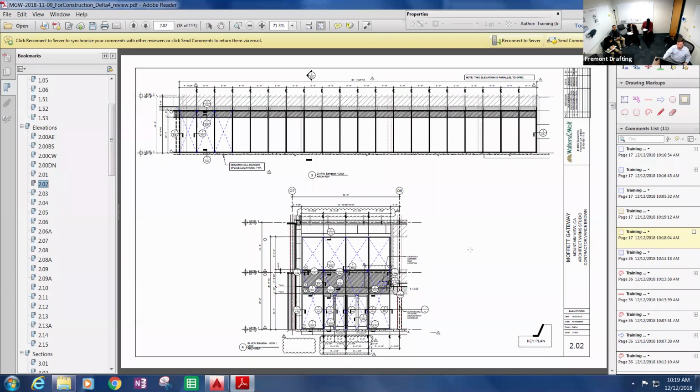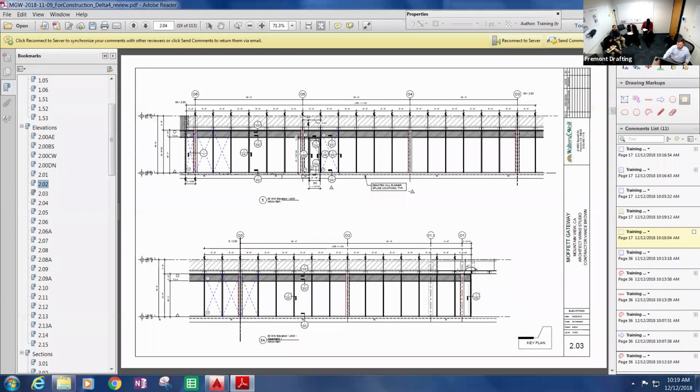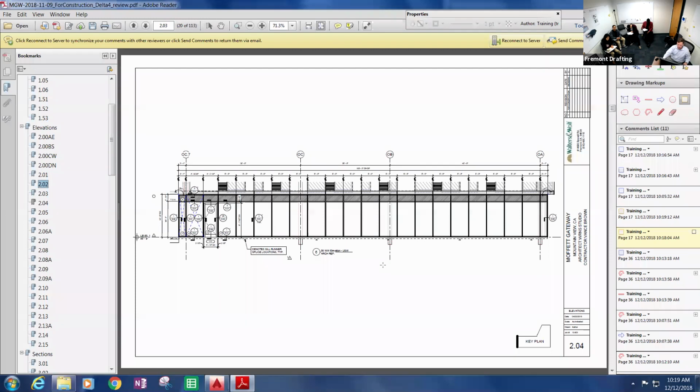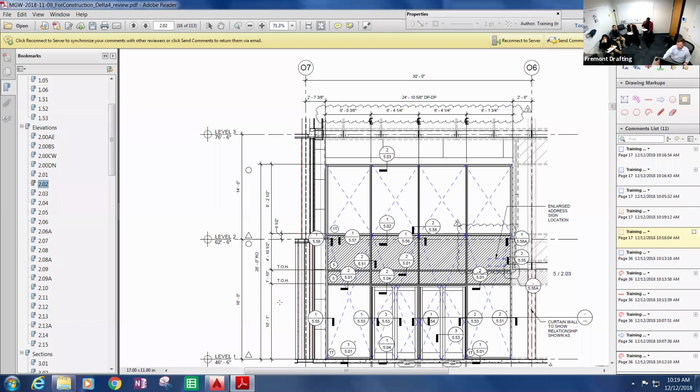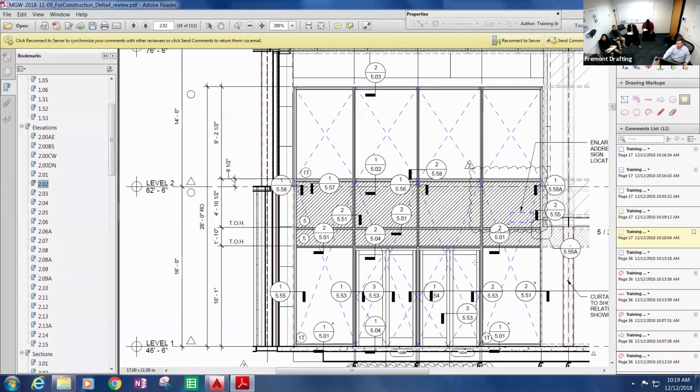And then if we go to... so that was one right there. If we go to a curtain wall, it's a little bit different. So our unitized curtain, the tributary area is still the same, but now let's say I'm looking for the deflection of this vertical mullion.